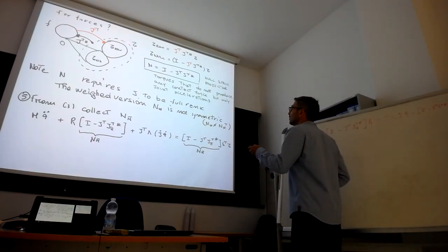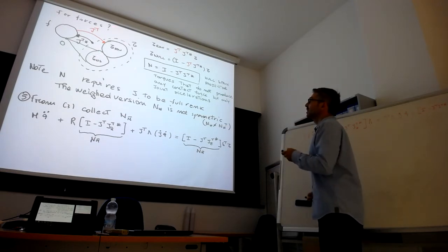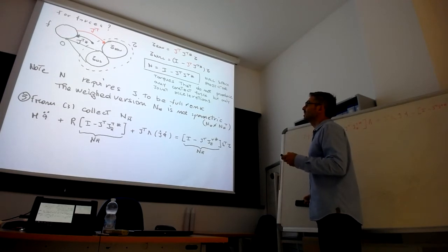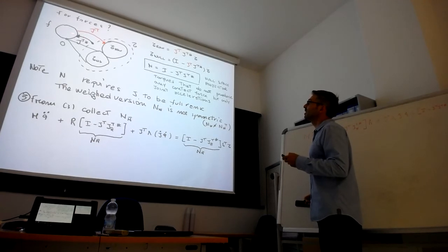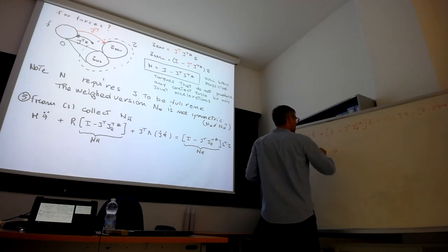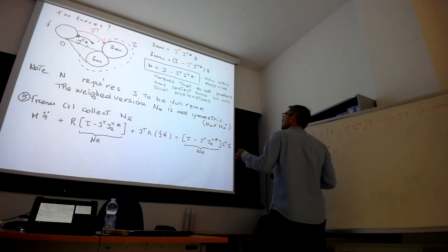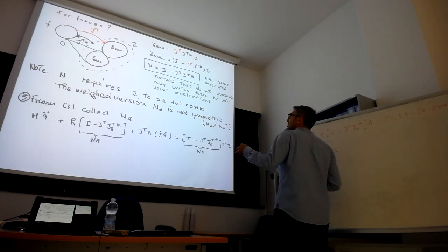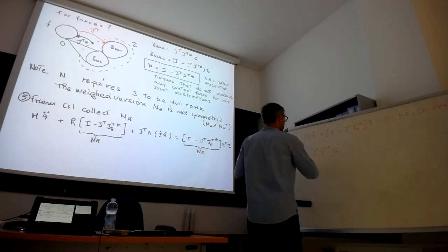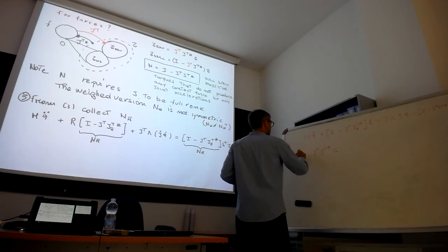you remember when we map from the space of the torques, that is n-dimensional, to the space of the end effector, that is lower dimensional than this, you can have a new space, and you map there with the J transpose Euler inverse. So whenever you have a vector tau and you multiply for J transpose Euler inverse, you filter out whatever is in the null space, and when you go back, you get in the row space. So this is a row space projector, and the null space projector is the orthogonal complement.